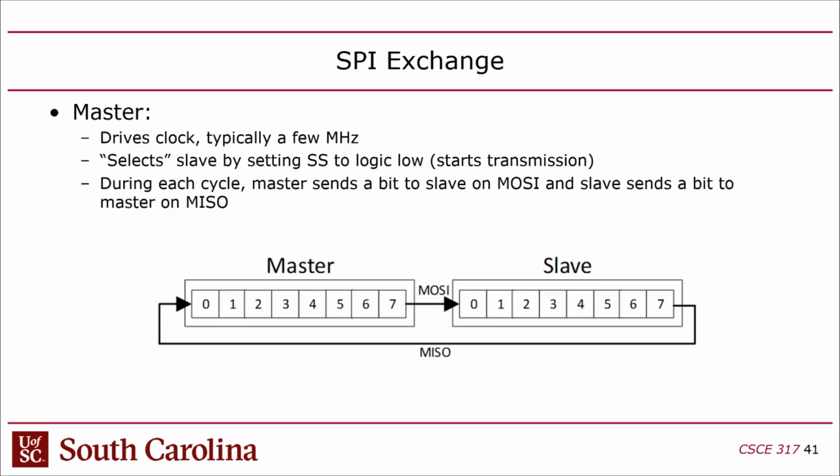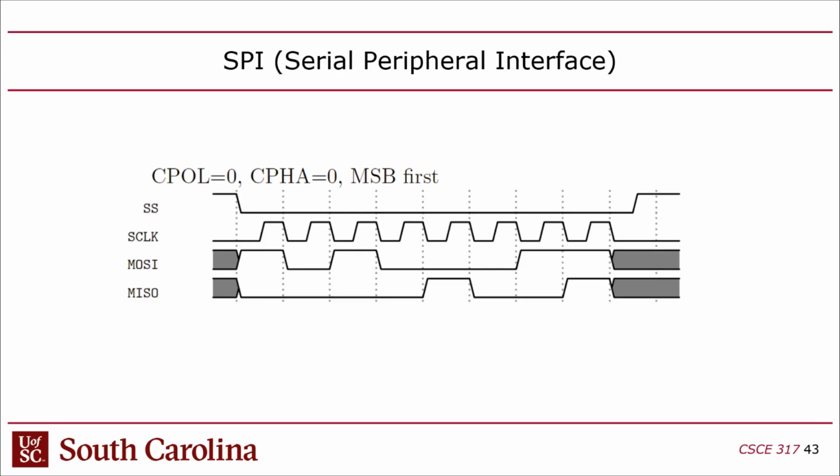Okay, then peripherals, SPI. Make sure you know about the CPOL and CPHA. You might say, what's the big deal with that? Why are you emphasizing that? Well, it turns out that if you use SPI, you have to be aware of that. If you want to do any SPI, it doesn't matter if you're doing a slave or a master or just buying two components off the shelf and wiring them together. You have to know what that is, because otherwise it's not going to work, even though it's a subtle difference.